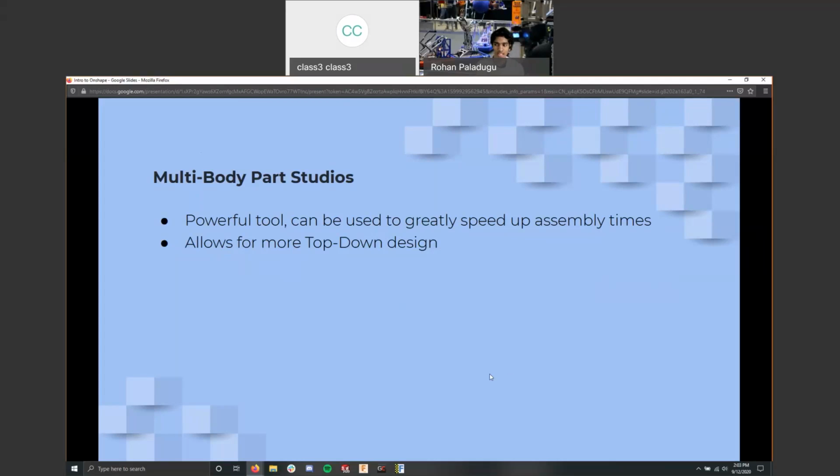So let's say I have 4 drive rails, and I'll demonstrate this in the demonstration where I will be designing a West Coast drivetrain. I can use part mirroring to take my left side and my front side drive rails, and mirror them to get my right side and my back side.